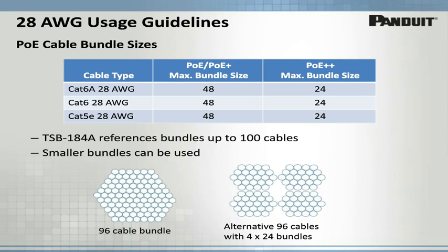It's simply an issue of when you bundle cables, and again, when we say bundle, we're talking about tight bundles of cable that can't breathe next to each other. The cables individually can certainly carry the current.